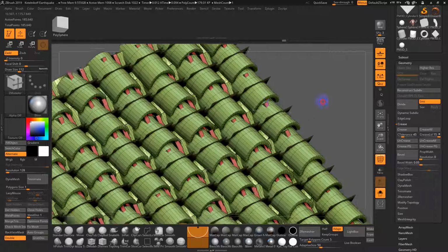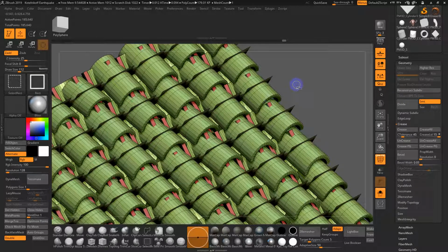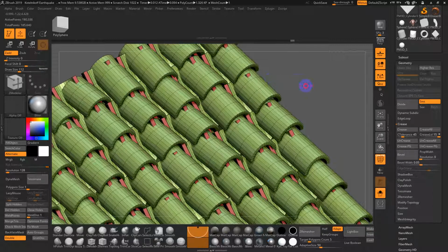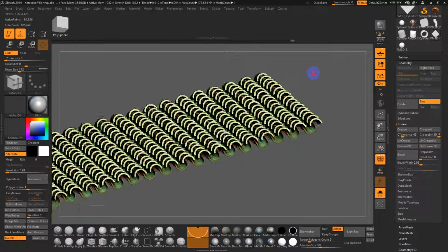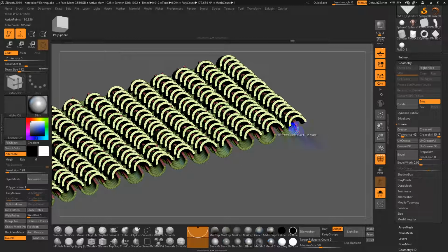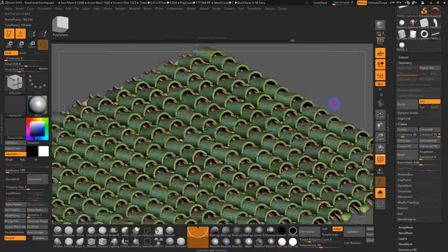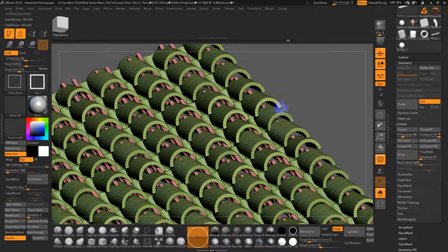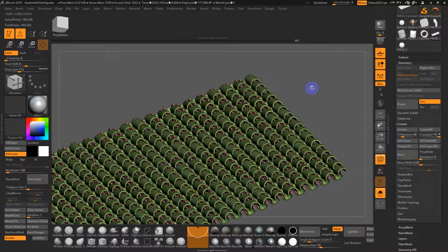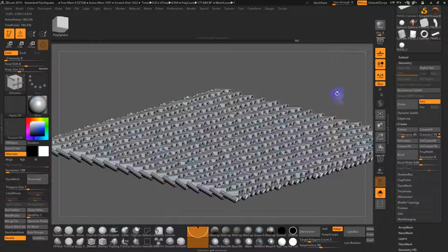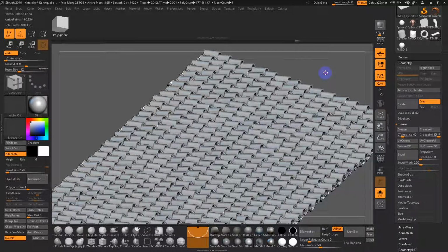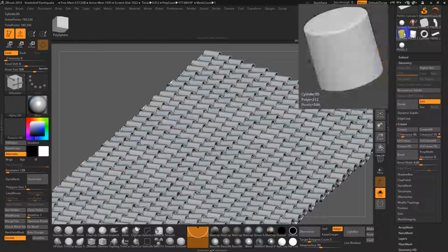And if you take a look, there's technically like 2 polygroups. There's this stuff, and then I can hide that off. Now, you can see that I'm getting some weird collisions from the under tile there. So usually I just do 1 row on top and then ignore the stuff underneath. But you want to isolate or hide those planes because that's Nanomesh's placeholder. And we'll just go to delete hidden. And that's it. All right, so now you've got this nice, more organic feeling roof. So really, really fast, really simple.